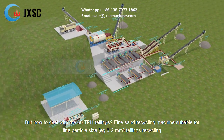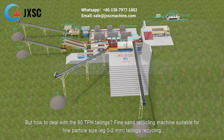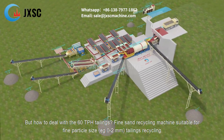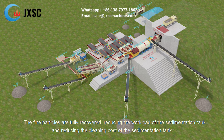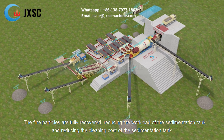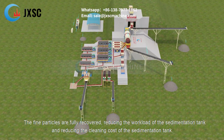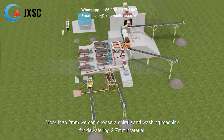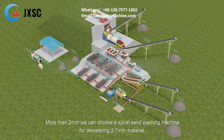But how to deal with the 60 TPH tailings? The fine sand recycling machine is suitable for fine particle size, e.g. 0 to 2 mm tailings recycling. The fine particles are fully recovered, reducing the workload of the sedimentation tank and reducing the cleaning cost of the sedimentation tank. For more than 2 mm, we can choose a spiral sand washing machine for dewatering 2 to 7 mm material.